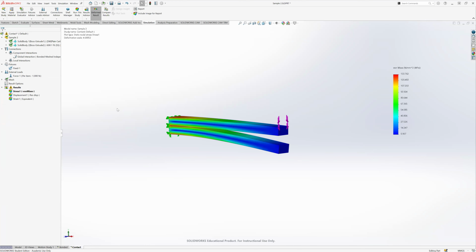So now I just changed the loads. If you just change the loads, you do not need to do anything with the mesh, and you see the mesh is still fine. So all I need to do now is rerun the study. And again, contacts are still going to take a little bit longer to run, and this is one thing to note while it's running.